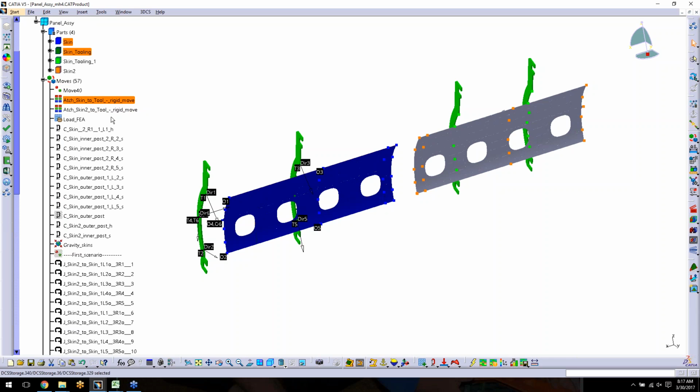First, we'll have the rigid body moves, which are simple fixed plane moves, and they are necessary for any compliant model. Then I did a different scenario for actually clamping the parts. For example, for the blue panel, I did separate clamping. First, I clamped the two top points, and then the rest of the points one after the other.